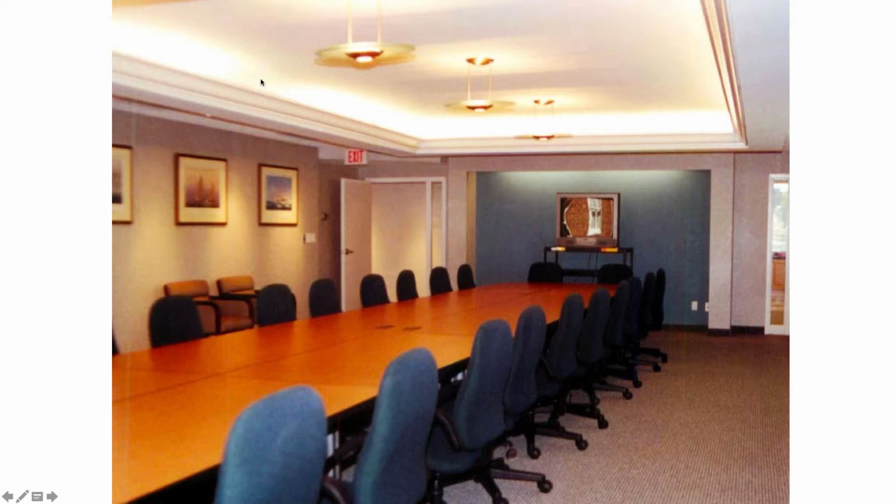You can see a bulb is out here, which is not so good. But here you can actually see the light distribution coming out of these. They're really trying to throw light up as high as possible. The big thing that's going to help you throw light up here, besides choosing a luminaire with a good throw, is the distance from the cove to the ceiling.